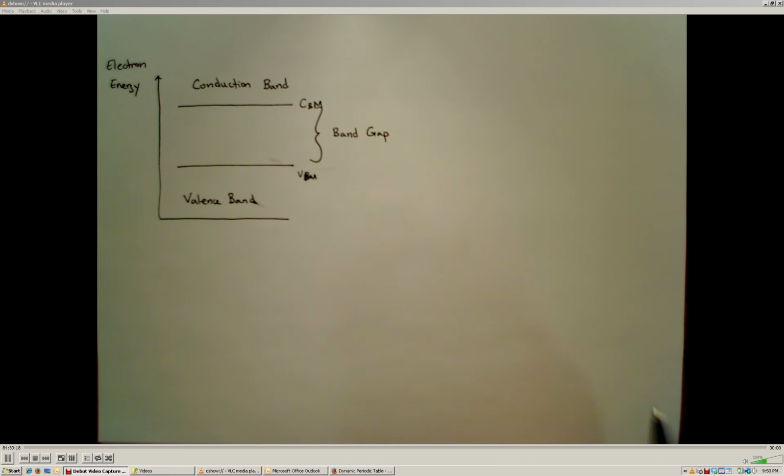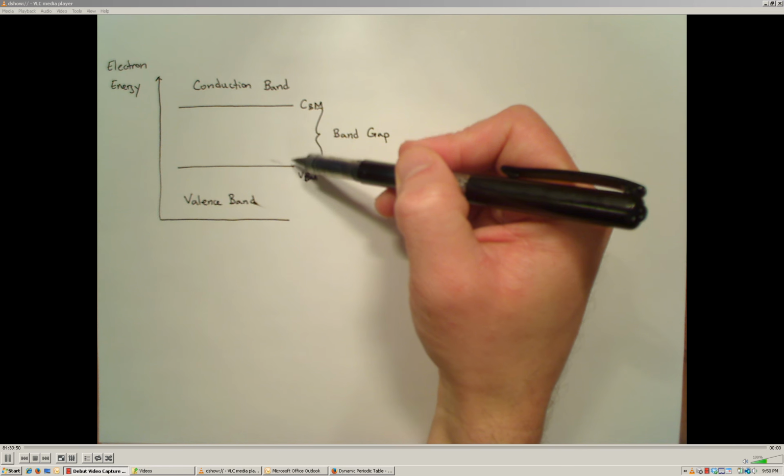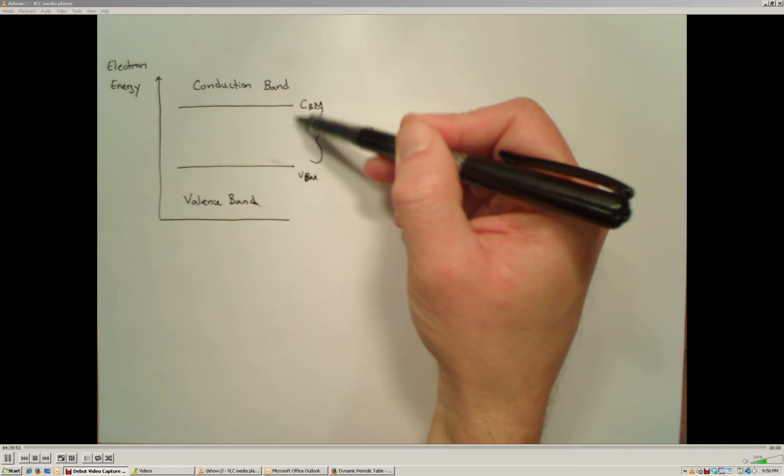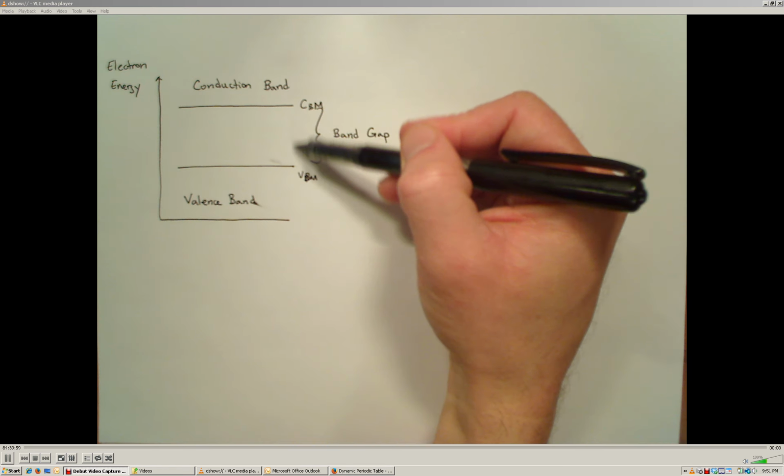Now, there's another thing that we need to be aware of conceptually, and this is called the Fermi energy level. Again, all of this is fairly complicated and derived from semiconductor fundamentals, which is not the intent of this course. But nonetheless, to be able to talk about these devices, we need to know some of the basics here. So the Fermi energy level is this imaginary energy level. Remember that no electron can have an energy that resides within this band gap region.